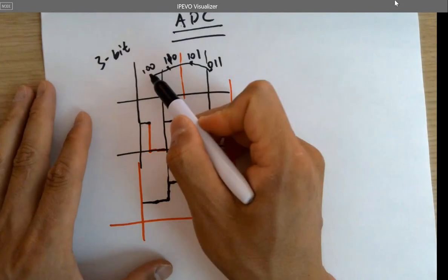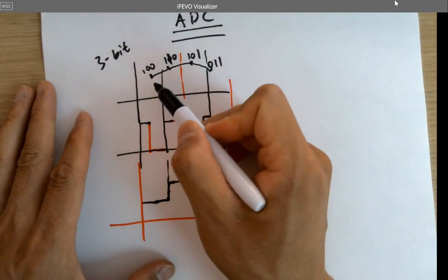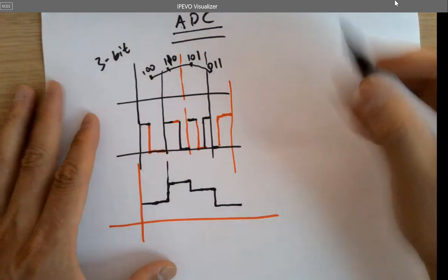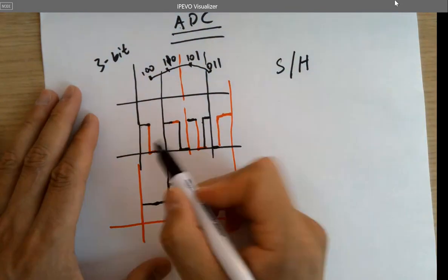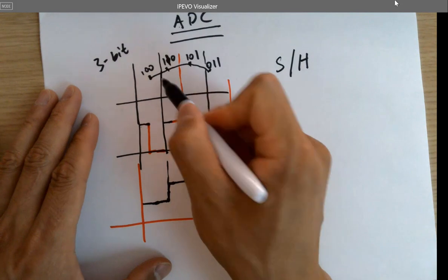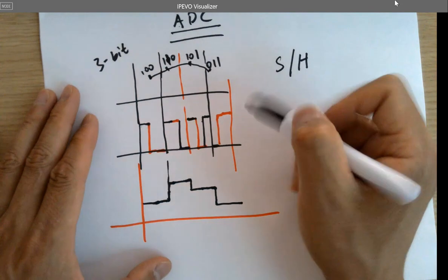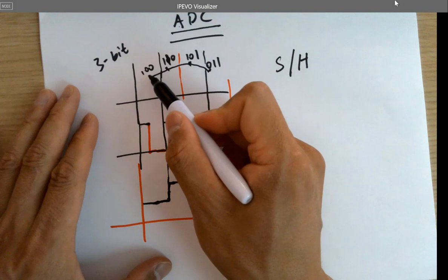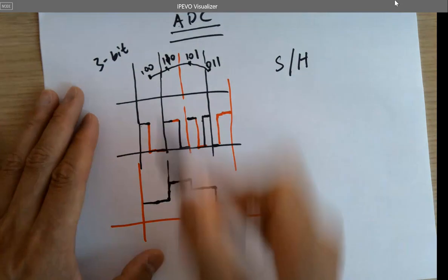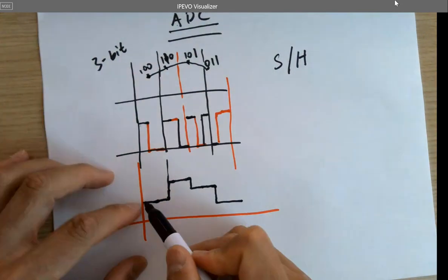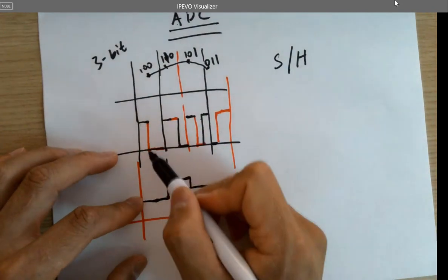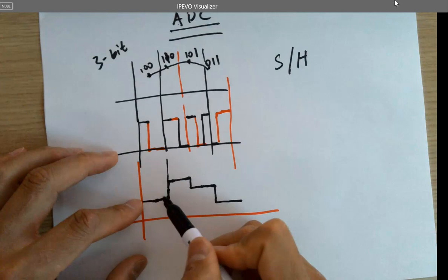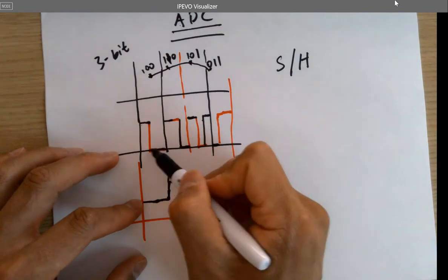This is a really good question, it samples it and holds it. There's a certain circuit called sample and hold. So it holds it until it goes up to the next value. Yeah, holds until the next cycle. So there are clocks controlling the cycles. So it samples this voltage and holds it in the capacitor for the conversion period. So the ADC is going to be super busy with the conversions and forming all the digits.